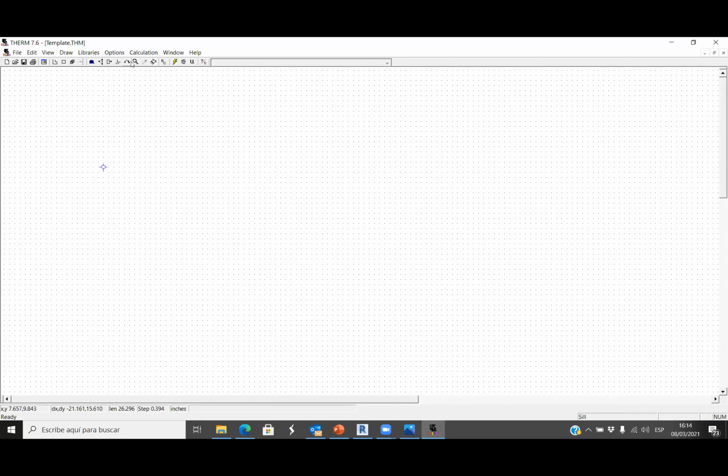You can select the zoom close to 20, and then start working in the middle of the screen. Do not start close to the edge, because we cannot extend the screen upwards, leftwards or rightwards. We don't know how big our detail is going to be. So just start drawing here.